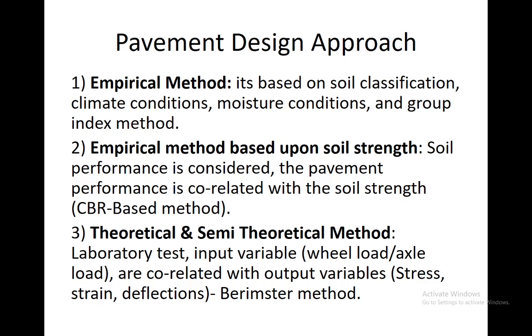The third part is the theoretical and semi-theoretical approach. This method is based on laboratory tests and input variables from the field such as wheel load or axle load, and also the correlation with the output variables such as stress, strain, deformation, and so on.